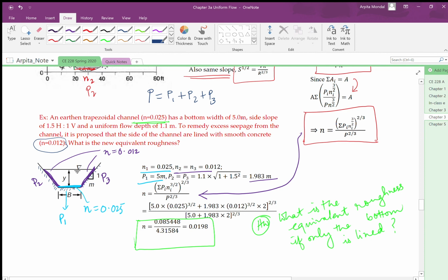So this sort of concludes our discussion on Manning's equation. One aspect that I need you to note here is that Manning's equation is valid for rough turbulent flows. It so happens that in nature, in most open channel flow that we encounter in reality, rough turbulent flow is what we expect. But therefore, when we are relating Manning's roughness coefficient with the Darcy friction factor f, you need to keep in mind that it is valid only for rough turbulent regimes. So in the next video, we are going to talk about how velocity distribution varies along the depth of the channel and so on. See you.